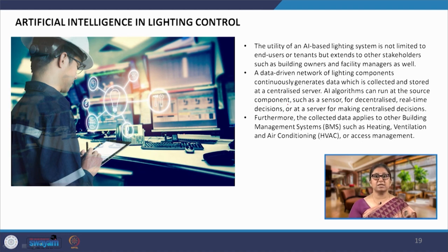What I was just mentioning is that we can write programs to override or to control. If there is natural light, the lux levels can be fixed: if we have, say, 400 lux from outside, then the internal lights would be turned on at, say, 25% capacity. As it falls down to 300, the internal lights may be turned on to 50%.